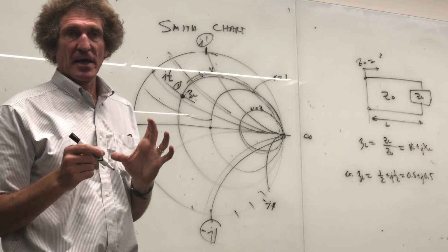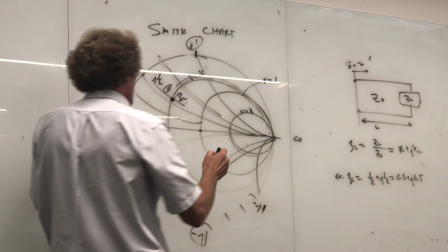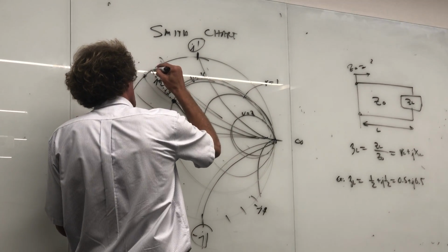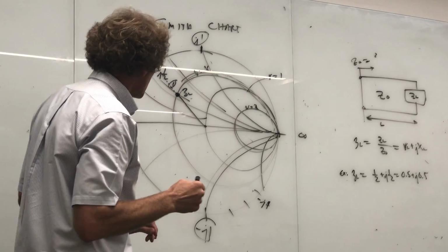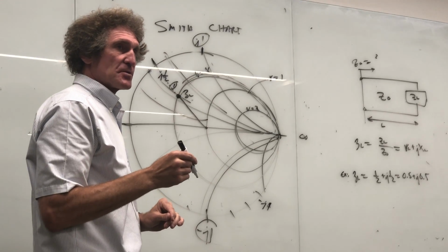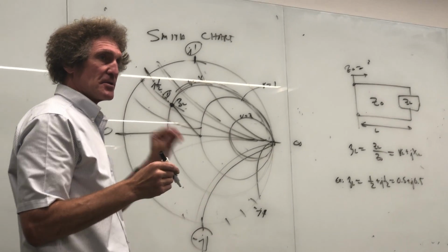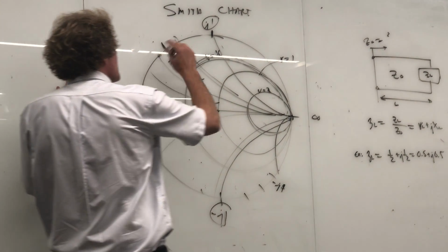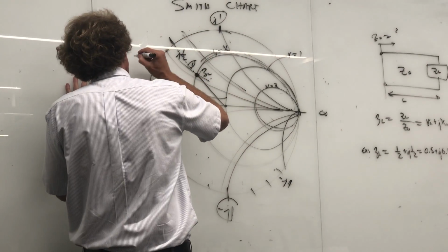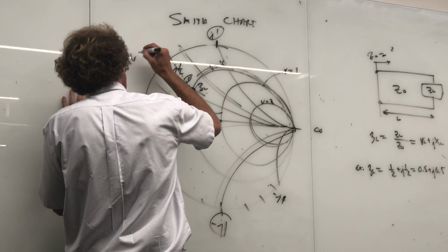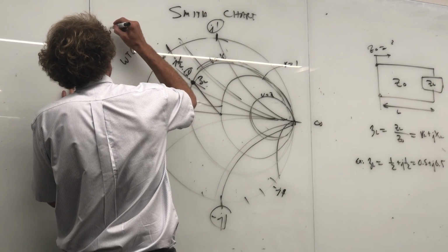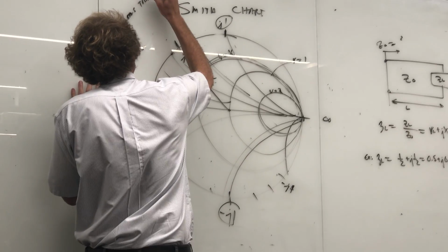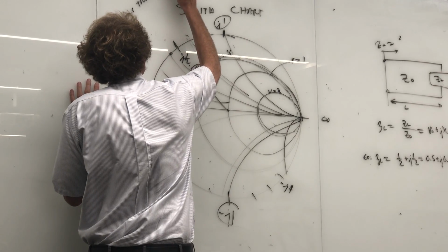Then you take your straight edge, or your compass really, and you draw a line from there to there, and carry it through and tap this point on the outer edge. When I give you Smith charts, it'll make a lot more sense, but the first time I like to do it just on the board like this. Now, out here, at the very outer part of the circuit, you're going to see something that says WTG. This is wavelengths towards generator.